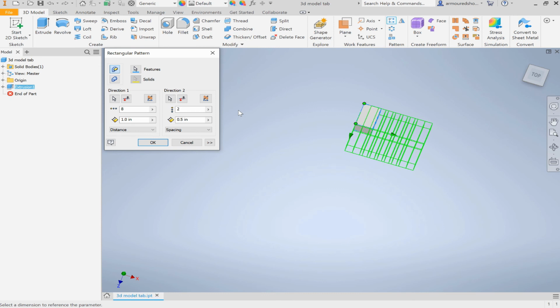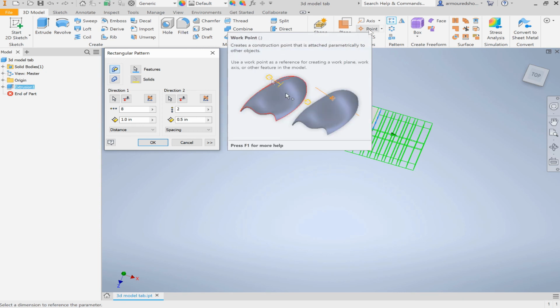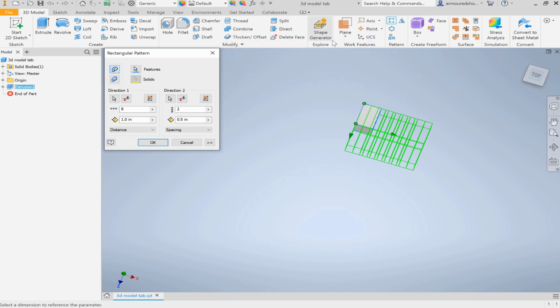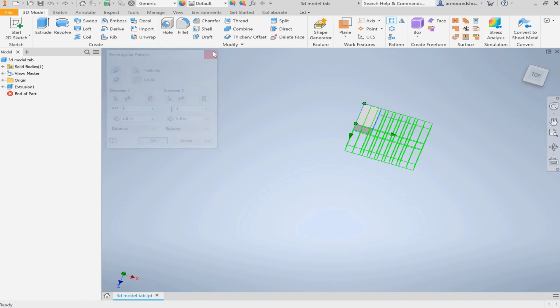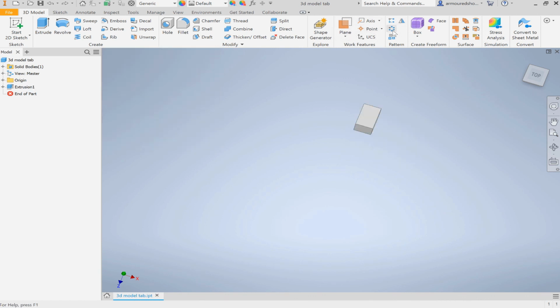This is very fancy, especially when you're trying to do CAD for the very specific VersaFrame poles that we use a lot, because you'll notice there is a bunch of holes in them. You can just make 1 point, and then use a rectangular pattern to zoom it across the whole pole, and then use the hole tool, and it'll do them in batches and punch a whole bunch of holes in there. And it takes about 2 minutes as opposed to an hour and a half to do it manually.